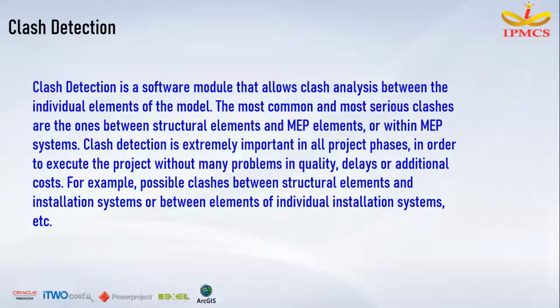Most common and serious clashes are the ones between the structural elements and the MEP elements, or within the MEP system. Say for example, in the MEP system itself, the electrical system and the HVAC duct, or clashes between ceiling or slab and beam, or wall and beam. So you can exactly find out and locate those clashes in the 3D visualization in the Bexel Manager software.